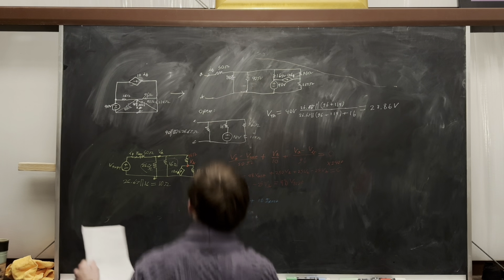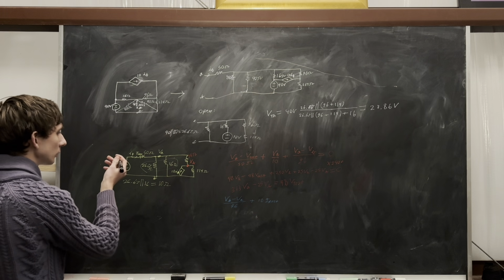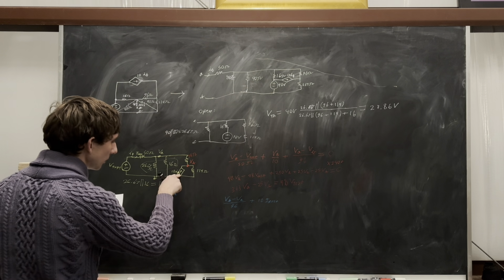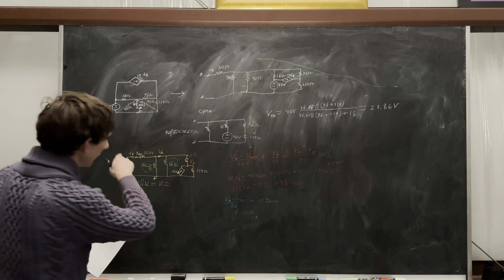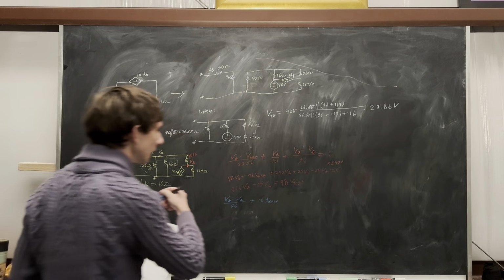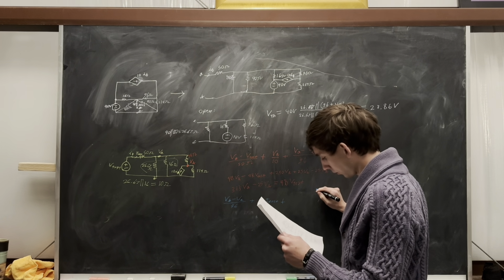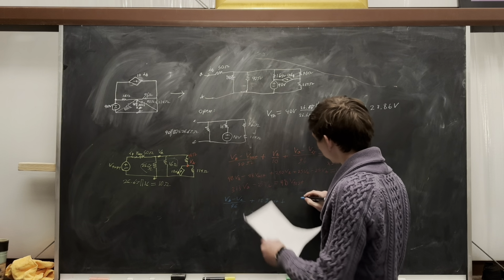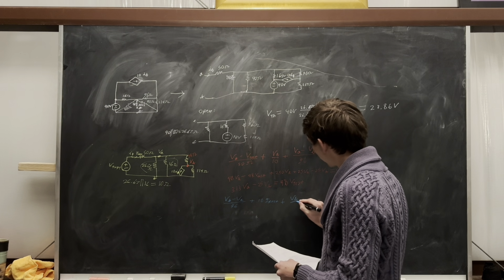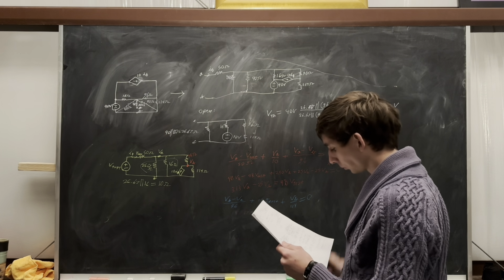You can see from this that IC and I test are going to be the same, just flipped. So if we flip this current source and just call this I test, we can get rid of the whole phi nonsense. Plus 10 I test plus VB over 114. That'll equal 0.